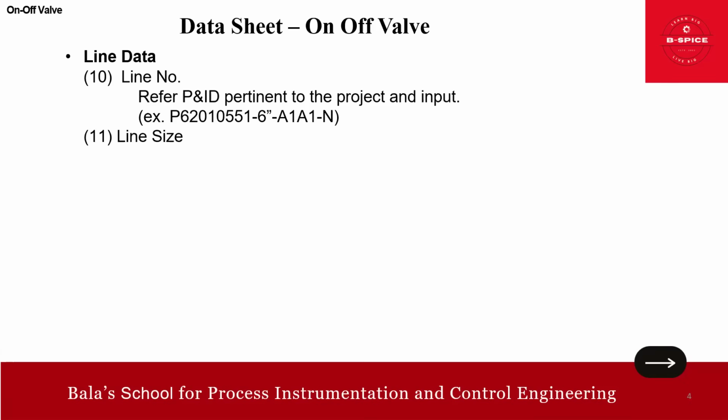Then we'll talk about the line data. Very, very important actually: the line number. Refer to the P&ID of the project and input it. This is the line number. If you have any challenge in reading the line number, we have uploaded a video, in fact our first video, on how to read a P&ID. You can watch and get benefited.